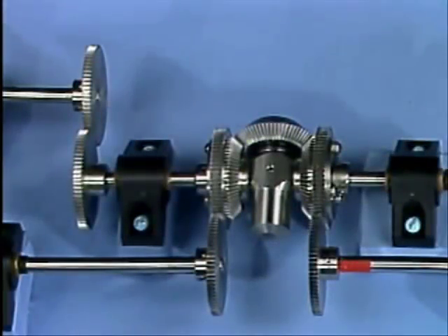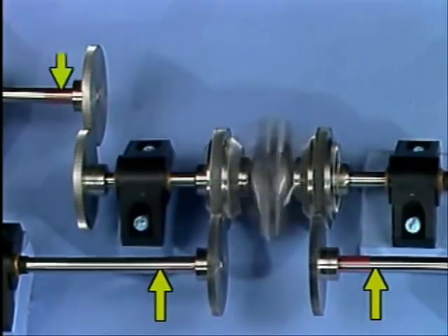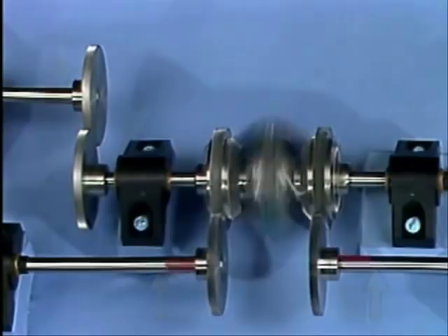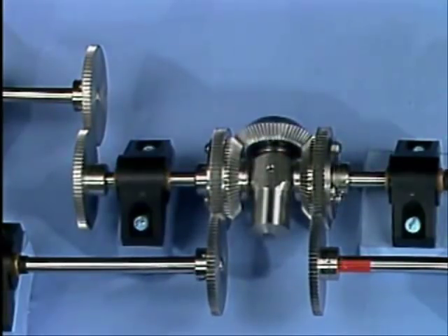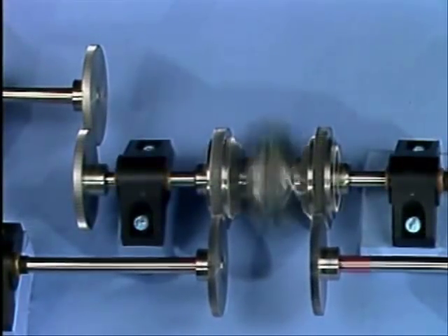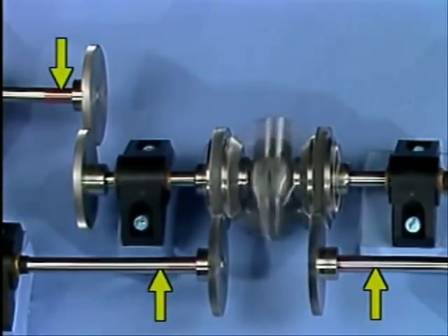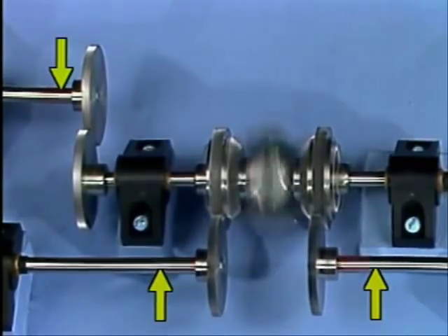Okay, now let's see what happens when these two shafts are turned. As you can see, this shaft turns. As we've seen from this example, a differential can have multiple inputs or outputs. Another function that a differential performs that's less obvious is its ability to compare multiple inputs and provide a corresponding output. Right now, this differential is comparing the speed and direction of rotation of each of these two inputs and providing a corresponding output on this shaft.